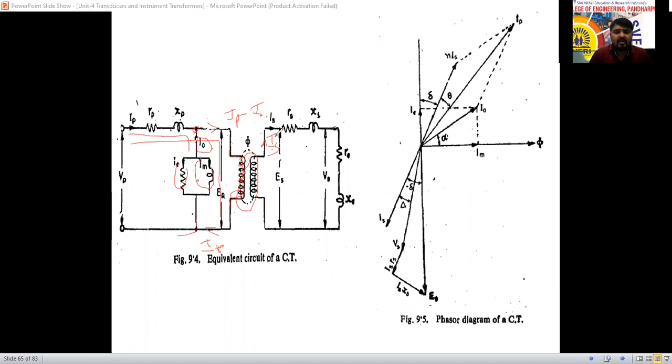So in that secondary winding, the current will flow, that is called IS, which will flow through RS and RX, and at the output side we are going to get the output load, or we can add that one here. So the voltage across this one is the secondary voltage, and the voltage across this one is the induced EMF. So this is the equivalent diagram of a single phase transformer.